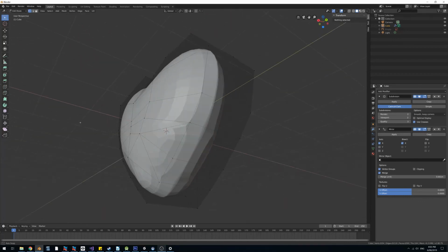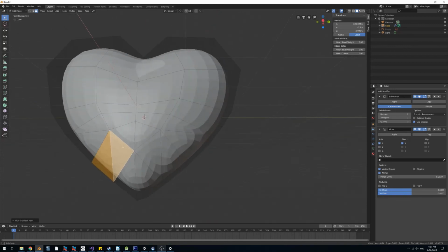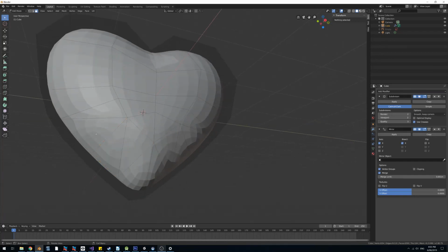So now that I've got these cuts, what I'm going to do is I'm going to change where those original edges were. So if you look at this system here, I'm going to go into face mode so I can select some faces. If you look here and here, this is now a 4-point mesh face that I could create if I could get rid of this edge. And the same can go for here. If I select here and select here, if I delete this line in the middle, I'll have what's called a quad, a 4-point face. And that's really what I'm trying to achieve.